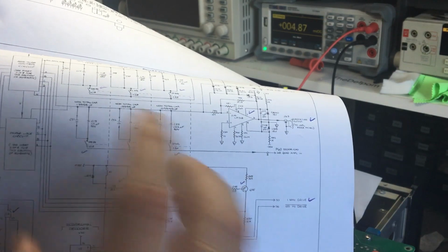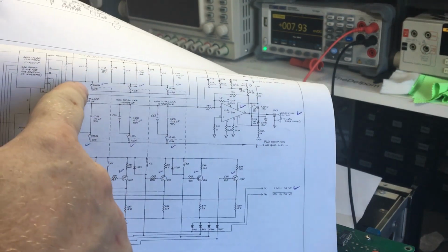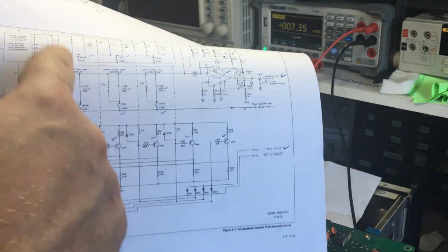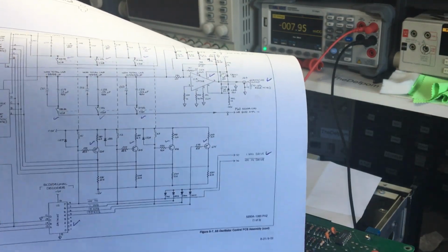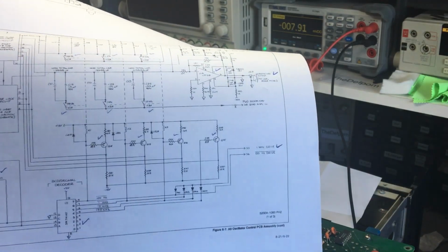I've ticked them because from what I've seen from the frequency control and the levels and stuff like that, it all looked okay. Maybe apart from 100 hertz. Was it 10 hertz? No, 100 hertz range. It looked a bit low, so it might be an issue with the 100 hertz. So I'm a little suspicious about one of those. I'm going to check those.